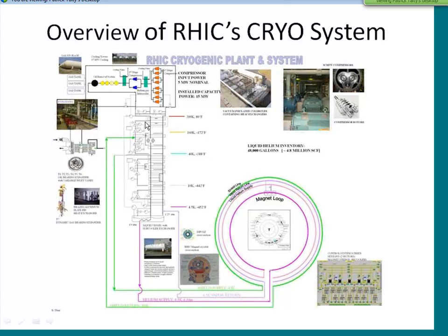As the gas gets colder, we kind of bootstrap on that, and we take the cold gas and make it even colder. And that's how we go from room temperature down to negative 450 degrees Fahrenheit, which is the critical temperature that's necessary to achieve superconductivity of the magnets. And these magnets, not unlike the magnets in an MRI machine, are used in this application to steer and focus the particle beams. Okay, and this is some of the industrial hardware that's used to accomplish this.